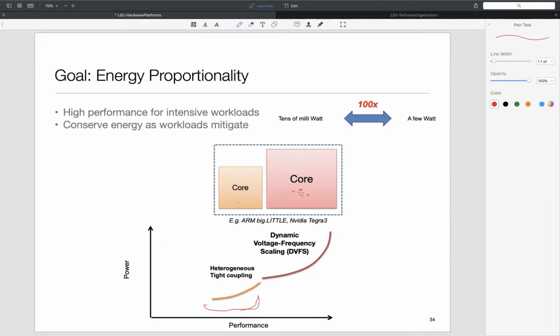So from an instruction set architecture perspective, both the cores will have exactly the same view. You can take literally the same software and run it on either one of them. But all these microarchitectural details, the under the hood stuff, cache and number of ALUs and these kind of things, they vary.